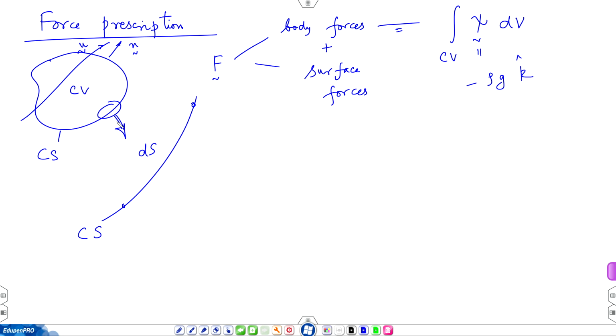So, to understand sigma, the stresses acting on this element, we may decompose the element into its Cartesian components. Why Cartesian? Because we have looked at sigma prescribed in terms of its Cartesian representation.